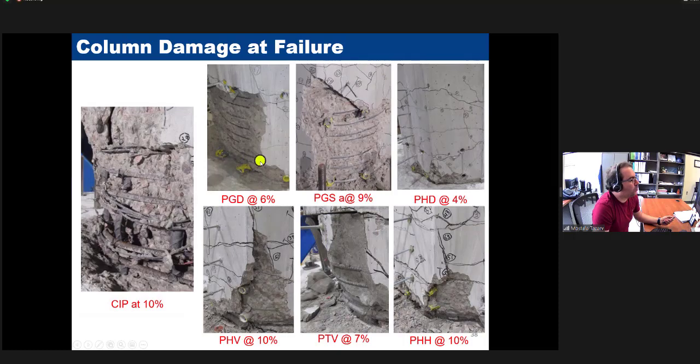And for the one with grouted coupler by Dextra, if you compare the two damages, you see that that one apparently has less damage. This is again because the couplers are big, stiff, and shifting the damage and nonlinearity away from it. And you can see a similar behavior everywhere. For PHT, you see on this screen, I'll talk about that later again, you don't see that much damage because it failed early on.